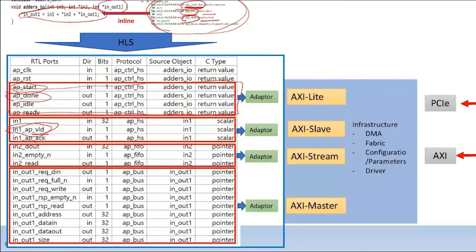It's an input, so the protocol generated is ap_fifo. For ap_fifo, in addition to the data, it generates two additional control signals, the empty and the read.